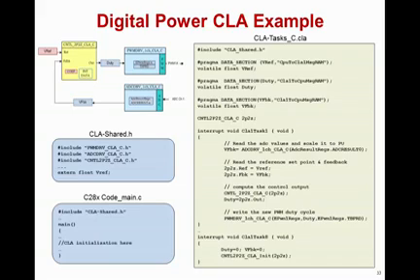So as you can see, we read in our feedback variable from our ADC, feed those two values, the reference and what was measured as the feedback, into our 2-pole-2-zero controller, run our control law code, and calculate a new duty that is then written to the PWM channel.